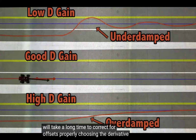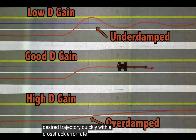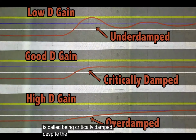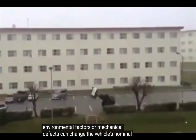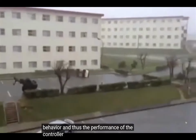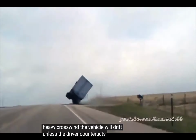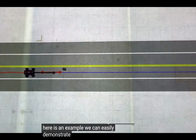Properly choosing the derivative gain allows the car to approach the desired trajectory quickly with a cross-track error rate close to 0. This is called being critically damped. Despite the success so far, for a complete controller, we're not done yet. Environmental factors or mechanical defects can change the vehicle's nominal behavior and thus the performance of the controller. For example, if there is a heavy crosswind, the vehicle will drift unless the driver counteracts this wind force with a corrective steering command. Here is an example we can easily demonstrate.